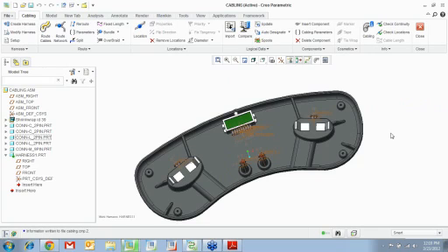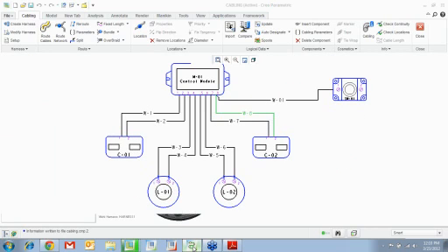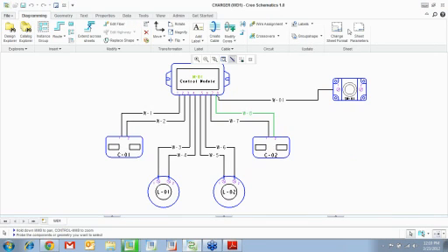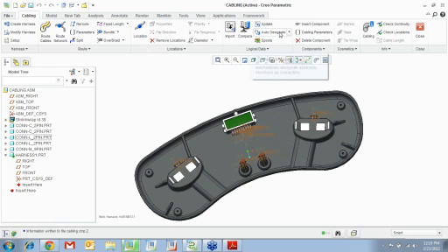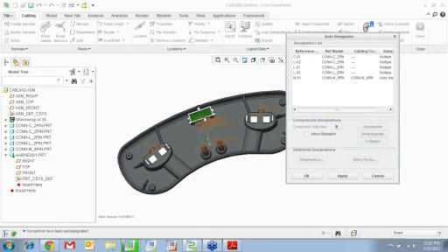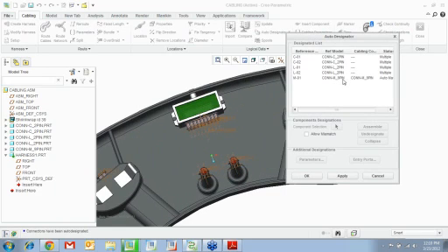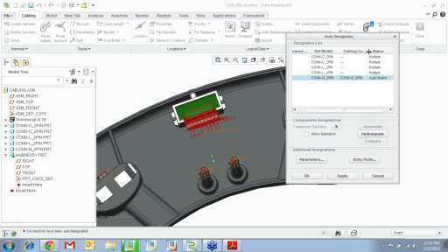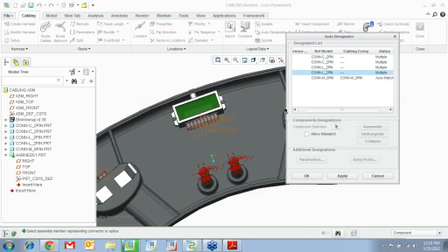Now, next thing we're going to do right here is to designate. I want to designate this component to be the same as this component, right? So you have to designate it. For that, we have something called auto designate. Click on that. You see that it finds there is only one unique connector 9 pin part. So it matches that with your cabling symbol, the routed system designer symbol. Notice that there are multiple instances of these parts, so you have to manually do this.